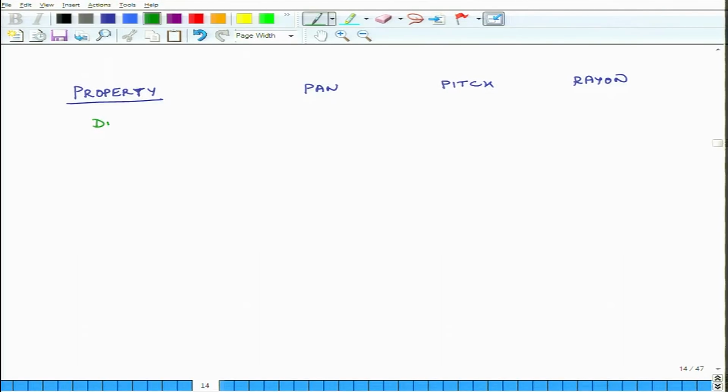First, let us look at diameter, and the units are micrometers. So, this is 5 to 8, 10 to 11, and this is somewhere in between, 6.5. Let us look at density, or specific gravity. So, this is 1.7 to 2. There is a lot of variation. Pitch is heavier, more dense, 2 to 2.2, and this is 1.7.